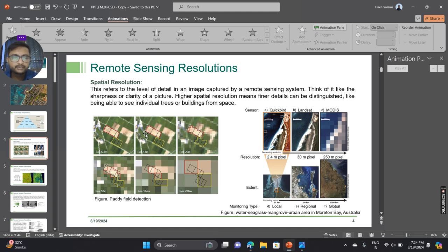What will happen if we want to make it 13? We will combine the 4 pixels of 6.5 meter, two on each side, so it becomes 1 pixel of 13 meter. Similarly, from 13 to 26, it will be 4 times again, so 4 into 4, 16 times compared to the original. Like in powers of 2, the number of pixels changes, and as we go, the resolution is becoming coarser.